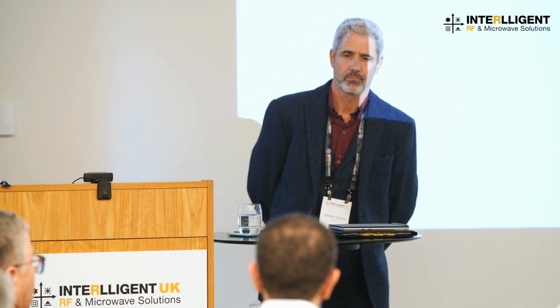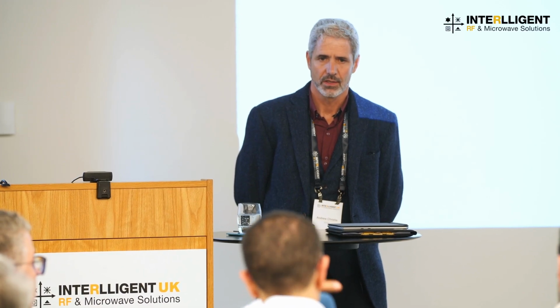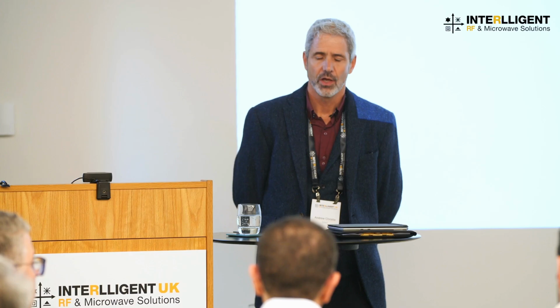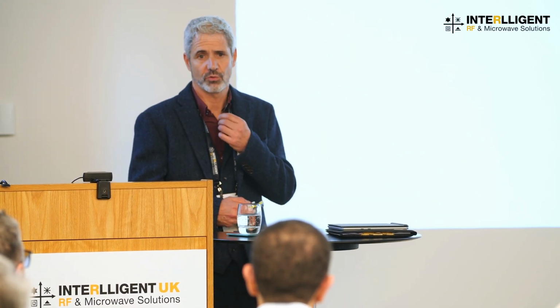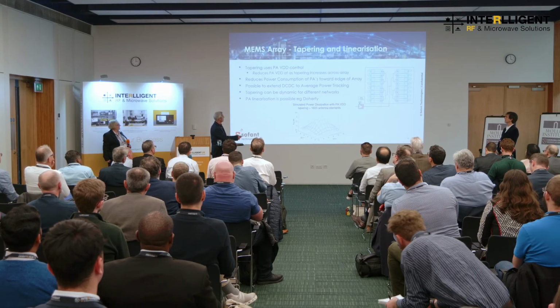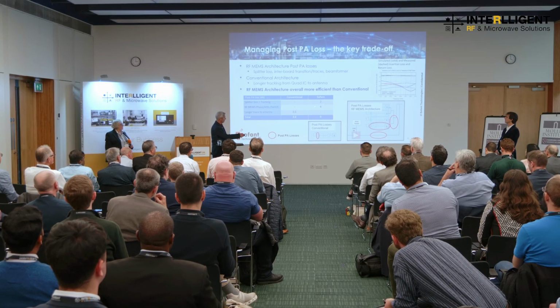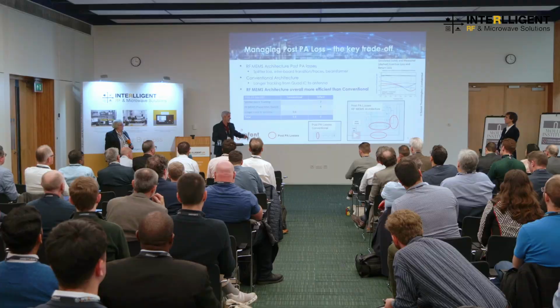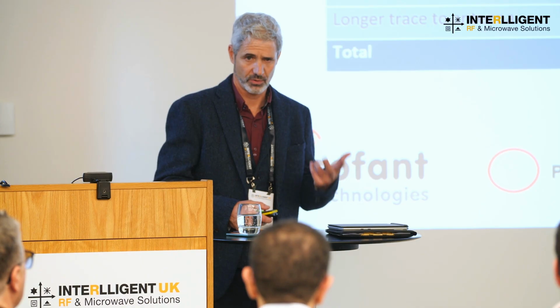Okay. And the second point, maybe I was confused. I didn't understand what's the difference between your architecture and the MEMS. So if you take your architecture but with another switch, like a PIN diode. So the reason you couldn't use another switch is the loss budget would go up. So where I showed, if I go back, the loss budget, the key is this number here. It's 4 dB. That's 4 dB for a 6-bit phase shifter, a 3-bit attenuator, and a switch.